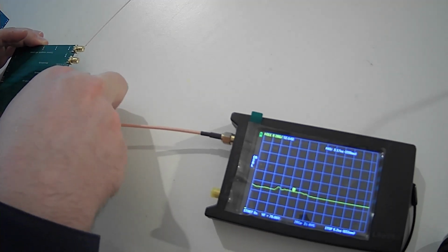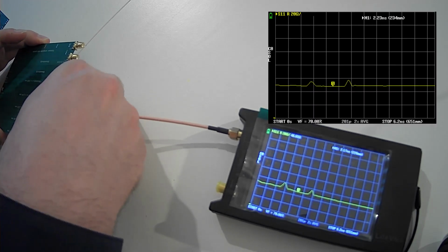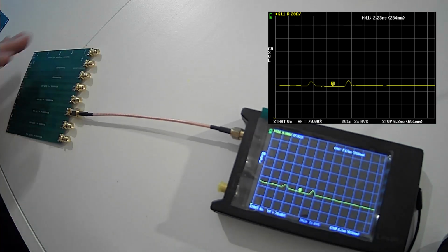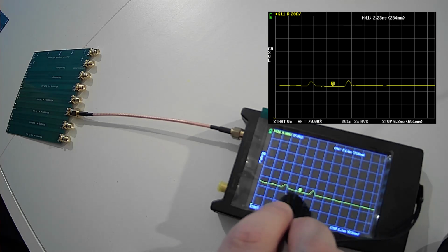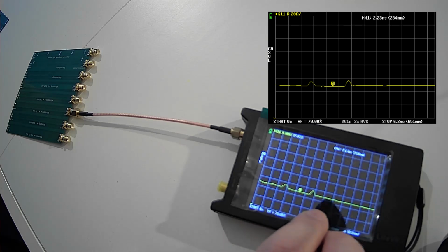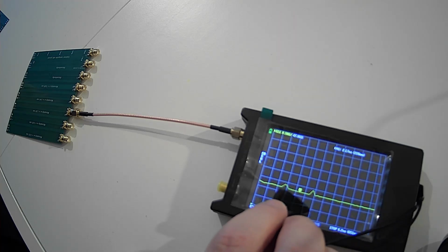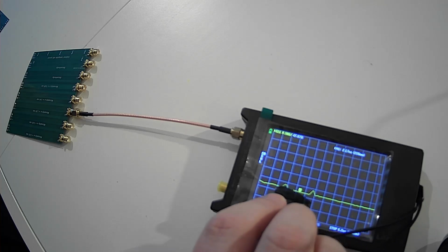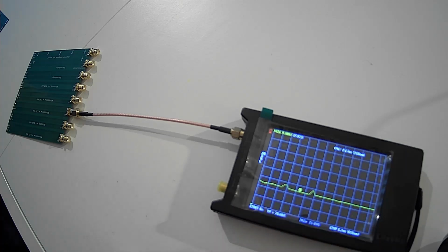So let's go to the next. It is 1.2 millimeter wide, and this is also the optimum design parameter for getting 50 ohms. So now you see here the value of this trace. It's very close to the 50 ohm termination resistor and 50 ohm cable. And you see here these two bumps. That is when the signal passes through the SMA connector, where the impedance is not fully matched.